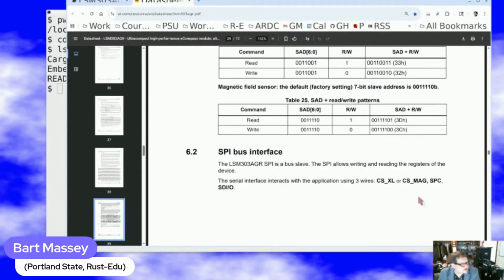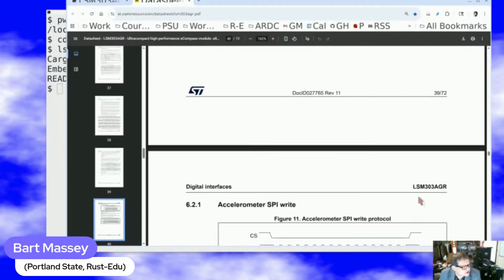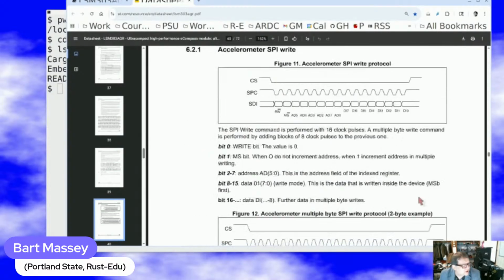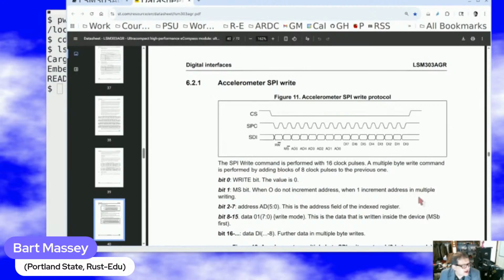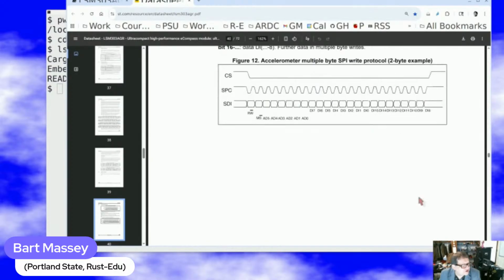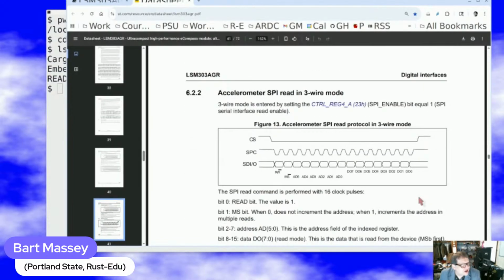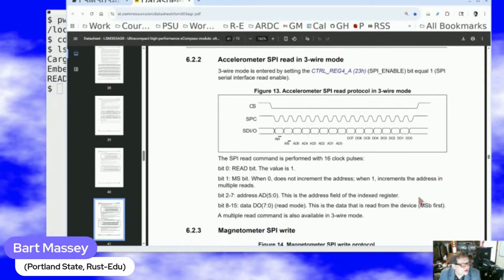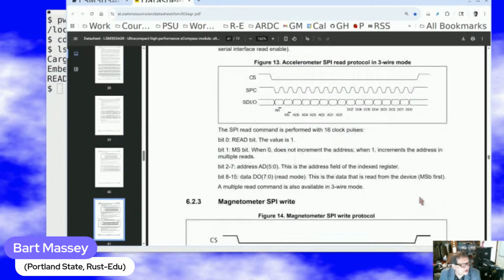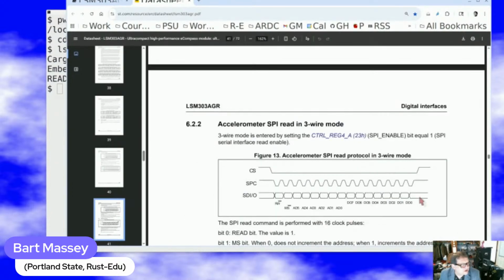And so there's this notion of registers. Almost all I squared C devices have this notion of having internal registers, which each have their own sort of register address. And you can read and write those registers to say what the magnetometer or accelerometer is doing and what it should be doing.